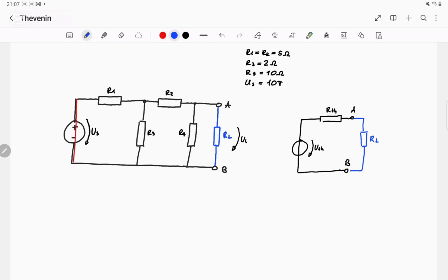In this particular case, that doesn't drastically change the circuit. However, in a different setup, such as when a resistor is placed directly in parallel with a voltage source, that resistor would be bypassed and ignored when calculating the Thevenin resistance. But in our example, the resistor R1 isn't bypassed because it's still connected into the rest of the circuit in a meaningful way. So let's walk through the process of calculating the Thevenin resistance.